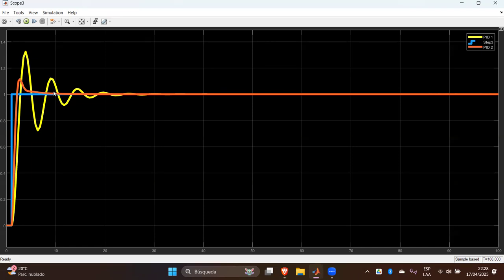but also you have the effect of increasing the oscillations. And the reason for that is that the integral action is quite similar to the proportional action, but in this case, we are generating these oscillations, or we are inputting more energy based on the accumulation of the error. Because remember that integral action basically adds the error over time. It's basically performing a summation of the error, and based on that accumulation of the error, we are adjusting the input energy into the system.